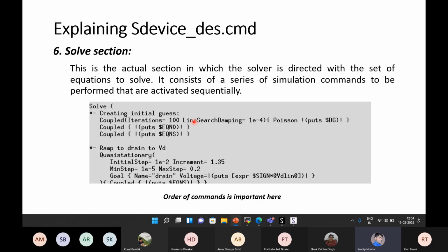If you want 100% accuracy, you need to make the mesh very thin or very small in size so that you get close to 100%, but you will never get 100%, because there will also be error. And there is another problem: if you go to a very small, thin mesh, your simulation might run for 2 to 3 years, and you cannot complete your PhD within the time frame. So it depends on how much you want and what time frame you have.